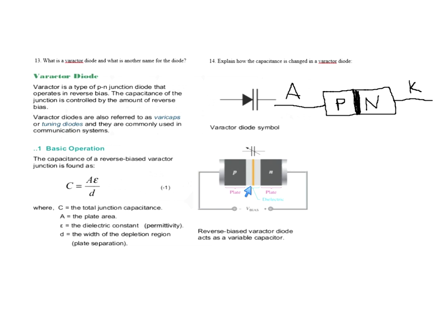Now, I can control the width of that depletion region. If I put a positive voltage on the anode right here, I can make that depletion region get smaller. And if I get up to about 0.7 volts higher than what I have here, that depletion region gets very, very small. And it eventually goes away, and it conducts. That's how a diode works.